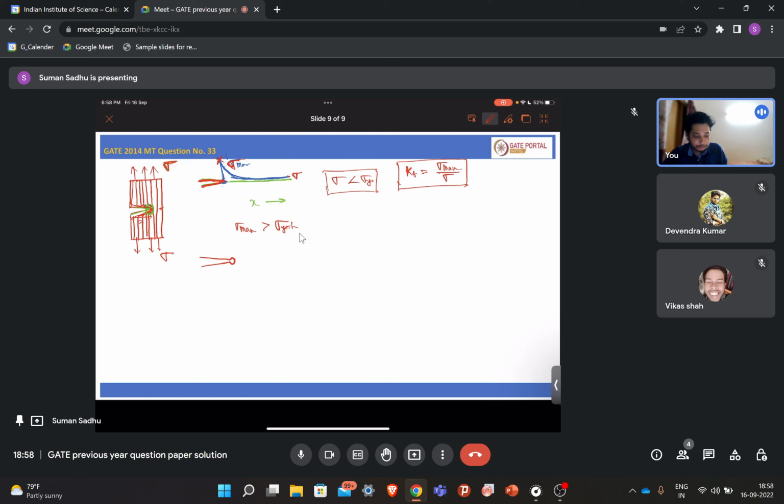Now if this sigma max is way too high, and even crosses your sigma fracture value, then what will happen? A crack will generate again because it will fracture this localized region. So your tip will be very sharp again. Again the tip will get blunted, and again it will get sharp. Like this, your crack will propagate. This is the way your crack propagates.